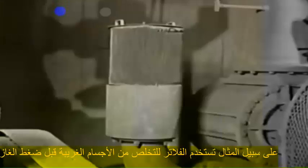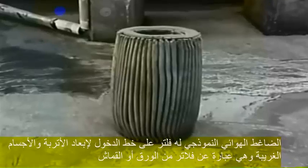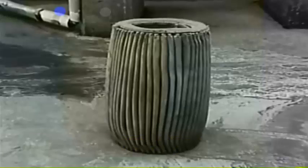For example, filters are often used to remove foreign material from a gas before the gas is compressed. If small particles of dust or other foreign material are allowed to enter a compressor, they can cause the compressor to wear excessively and eventually fail. An air compressor typically has some type of filtering device in the intake line to remove dust and other foreign materials. The filtering devices are often paper or cloth filters.